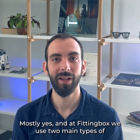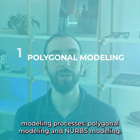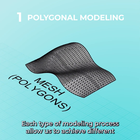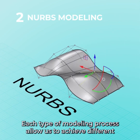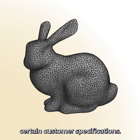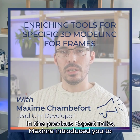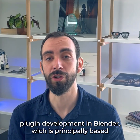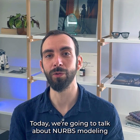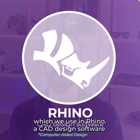Mostly, yes. And at Fittingbox, we use two main types of modeling processes: polygonal modeling and NURBS modeling. Each type of modeling process allows us to achieve different levels of quality, but also to respect certain customer specifications. In the previous expert talks, Maxime introduced you to plugin development in Blender, which is principally based on polygonal modeling. Today, we are going to talk about NURBS modeling, which we use in Rhino, a CAD design software.